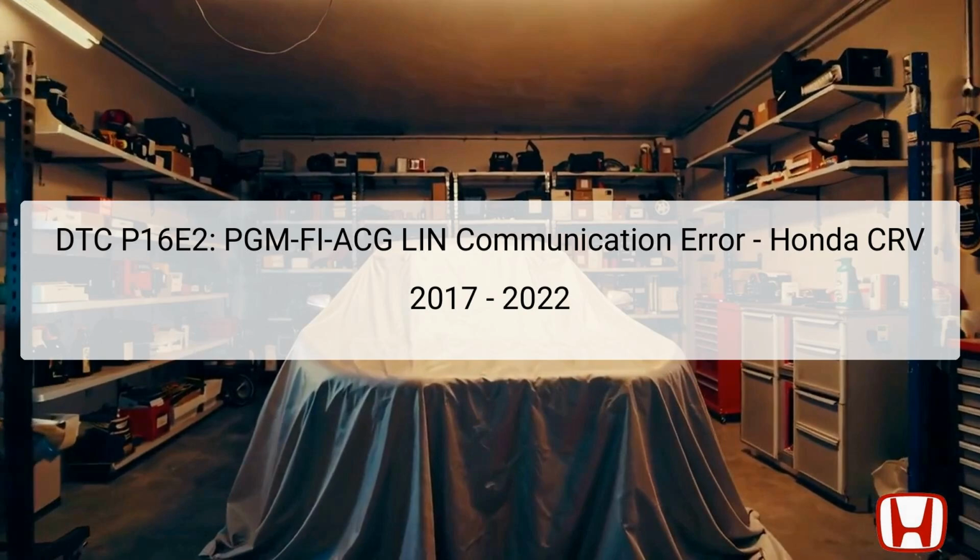The DTC P16E2, indicating a PGM-FI (Program Fuel Injection) ACG (Alternating Current Generator) LIN (Local Interconnect Network) Communication Error, is a critical issue that can affect the performance of the Honda CRV from 2017 to 2022. This error typically arises when there is a problem with communication between the alternator and other components in the vehicle's electrical system. The alternator, crucial in charging the battery and powering electrical systems, can be found mounted on the engine block.